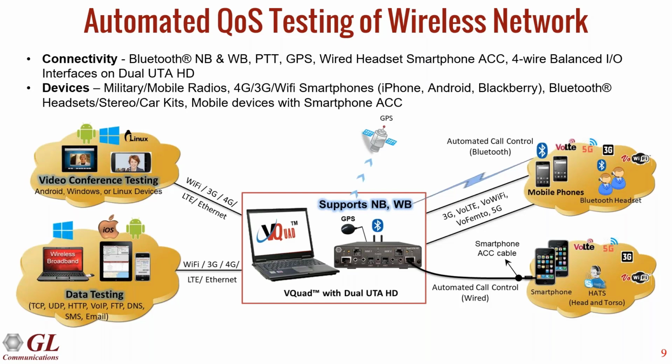So we'll get an event that says there's an incoming call, and we can automatically answer the call. With the Bluetooth, we can also send any Bluetooth command to the phone, such as what's the signal level, and we can convert that to an RSSI, or what network are we on, things like that, and then all the voices over the Bluetooth interface, or the wireless Bluetooth.